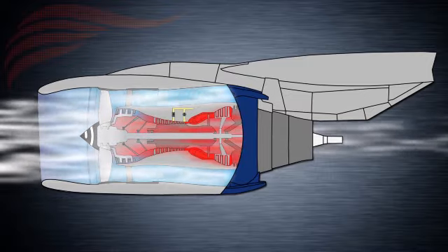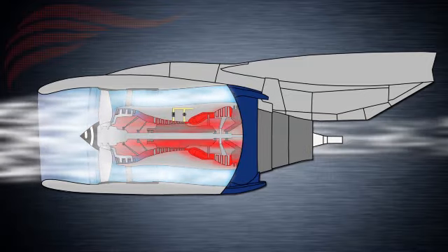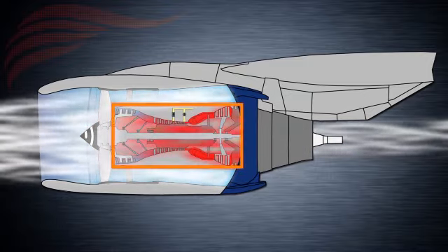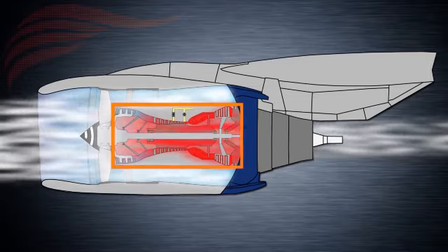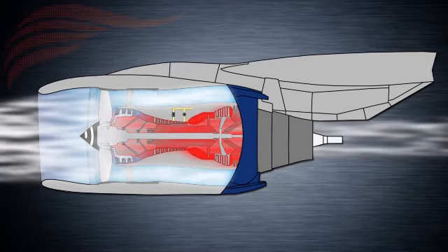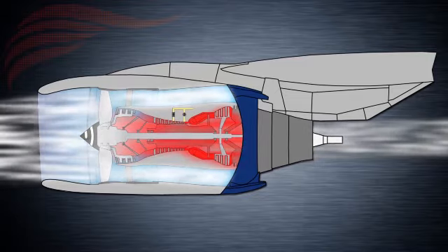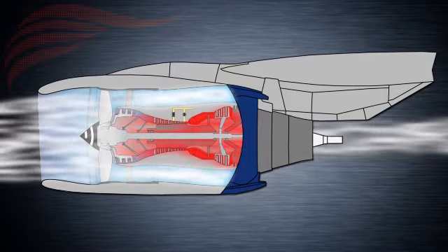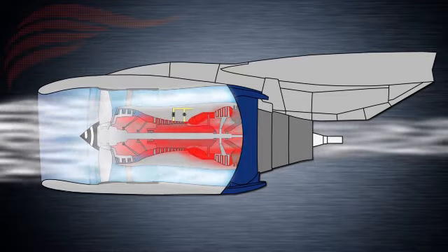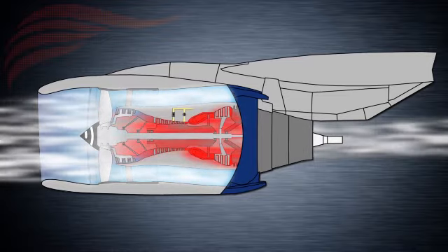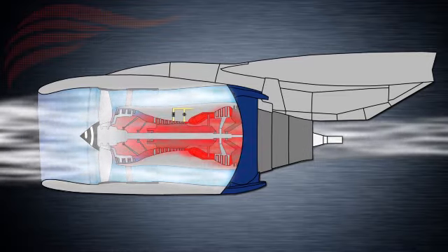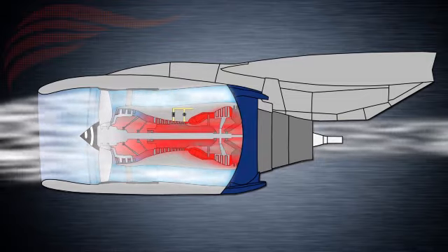After that, the air passes through a series of low and high pressure compressors that increase its temperature and pressure. Following compression, air is mixed with fuel and ignited in order to finally pass through a series of turbines that turn the respective shafts in the engine and thus turn the fan, causing a forward pushing force or thrust.